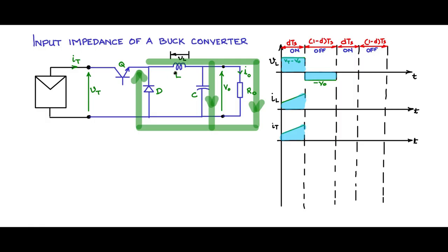And the inductor current, see, the voltage across the inductor is minus V0, and therefore the inductor current is now discharging, falling down with a negative slope of minus V0 by L, because VL is equal to L di by dt. The slope dIL by dt will have a falling slope of minus V0 by L. So this would be the inductor current within the cycle.